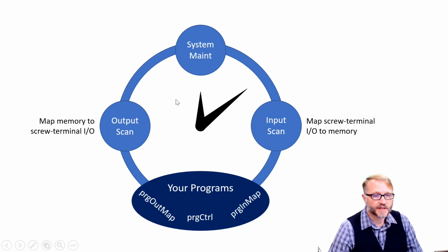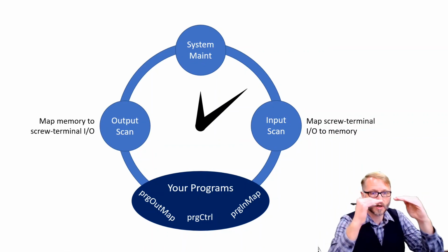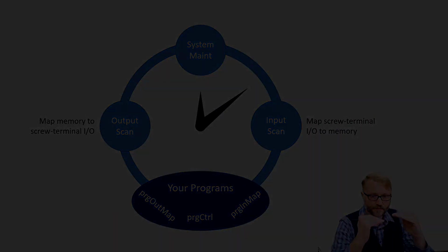You have to remember that the PLC is always going through this hardware-based operation where it's scanning the inputs, your programs do something, and then it sends that information to the outputs. But you also have to remember that your programs are scanned sequentially, and the PLC walks rung through rung through rung. Let's see if we can't represent the PLC operation using a spiral.